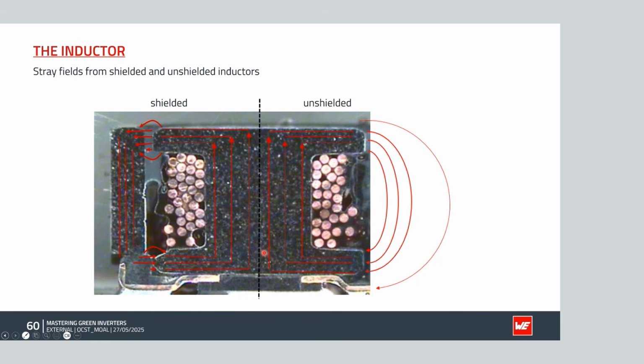We're talking about some of the hidden issues when it comes to shielded versus unshielded. With molded, you do not have that effect. You can go 20 degrees, 40 degrees, 60 degrees, 80 degrees surrounding air temperature, and your ripple stays the same. With a distributed air gap, there is very little effect on the BH loop and the saturation behavior of that inductor. So not only is it very good from an EMI point of view, but it's also good from a functionality as a storage inductor point of view. The question would be, why not use molded for everything? Maybe that's for another day.